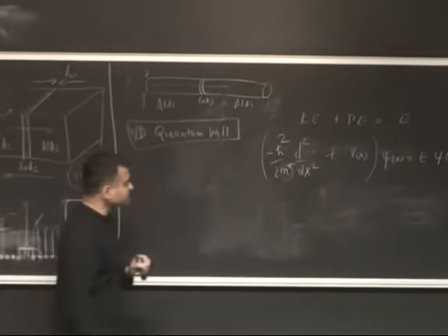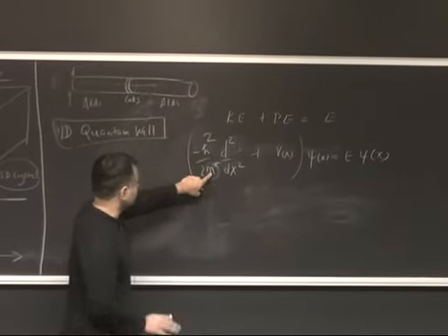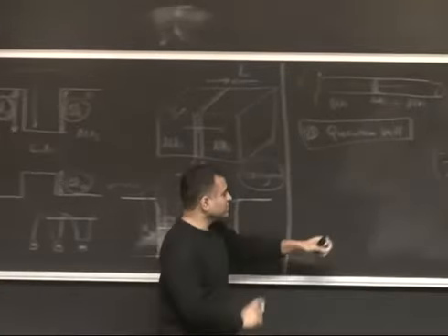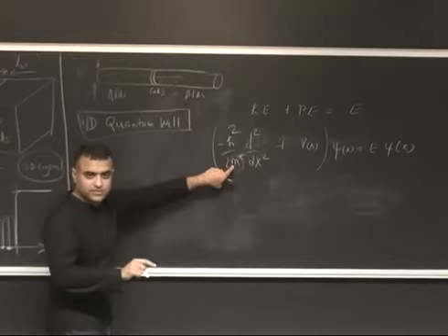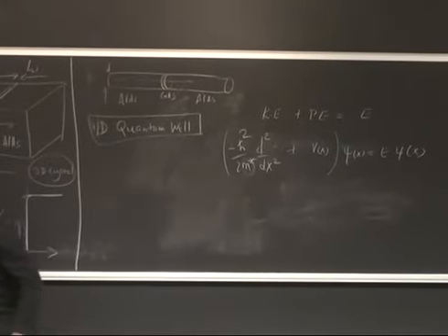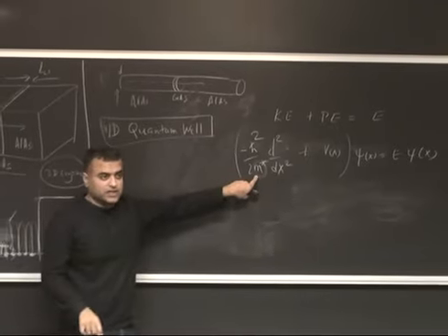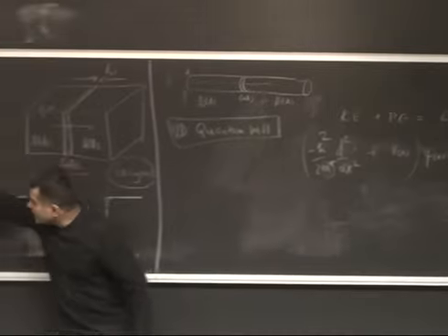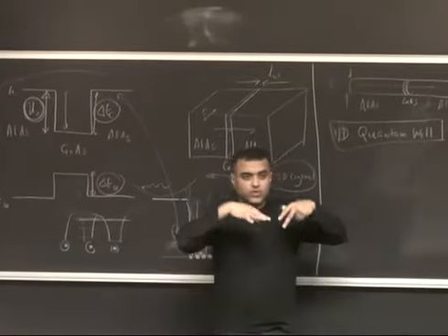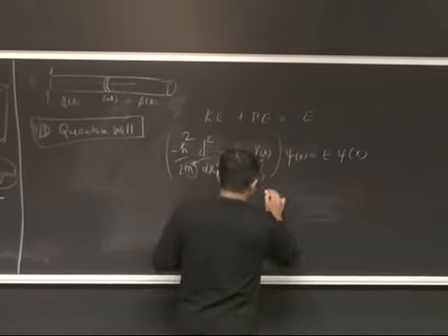But very importantly, you have to be sure what you're solving for. If you are looking for electron energies in the conduction band, you use the effective mass of the conduction band. If you are looking for electron energies in the valence band, you must use the effective mass of the valence band. Right? And similarly, you must use the valence band offset, not the conduction band offset, and all those details. Just be clear about which band we are looking at. Okay, and the potential is